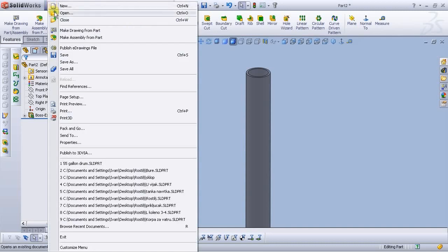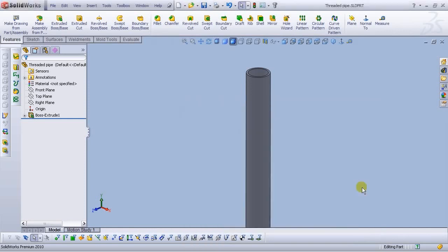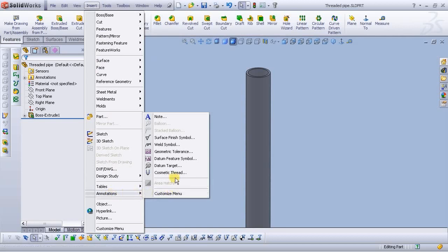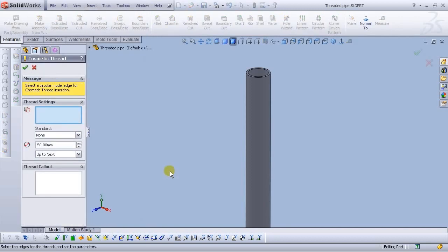And let's do offset entities and select 2 millimeter offset. And let's select reverse direction and select OK. Go to isometric view and go to features and Extrude Boss Base. Go to zoom to fit. For the depth, type 610 millimeters. Go to zoom to fit and select OK.